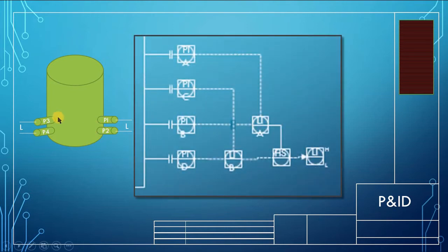If you are afraid that one of those nozzles will be plugged by, let's say, slurry or whatever in the tank, you have another set. So you have set 1 and set 2. Set 1 is pressure A and B, set 2 is C and D. A and B will give you one measurement of level. C and D will give you another level. Now you use one of them as your tank level.